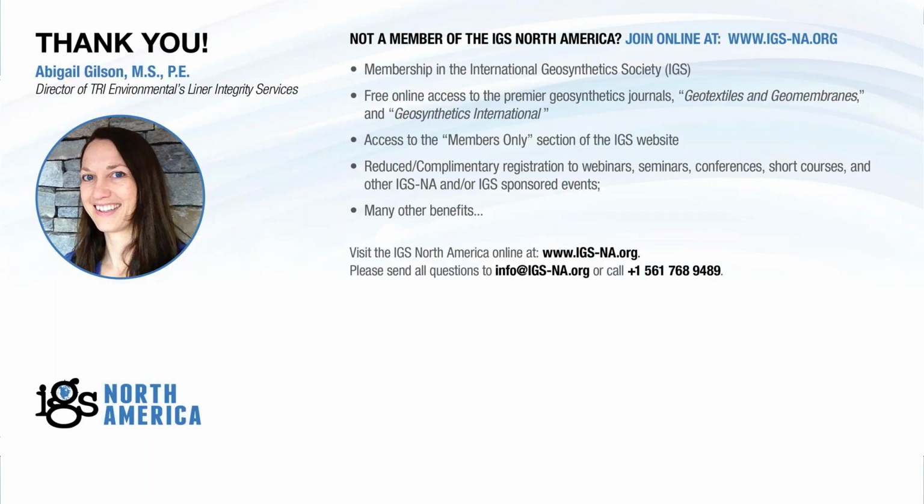You get the site response index. You say, okay, at this level of current at this site on this day with these conditions, this is what this means. You might have to do the survey once, but once you get that correlation, then you can come and do this quick test where you drop in your probe and, oh, I know this site. I know what it means. I know how much current an actual hole will draw. It's drawing 0, so I know there's no holes, and that's my quick test.